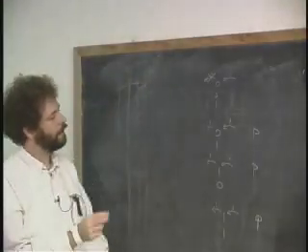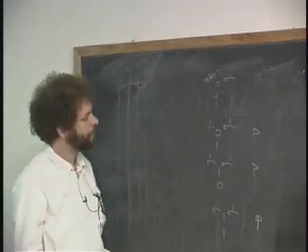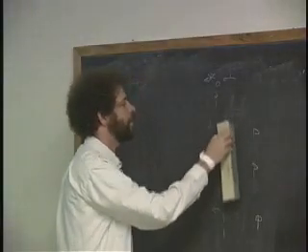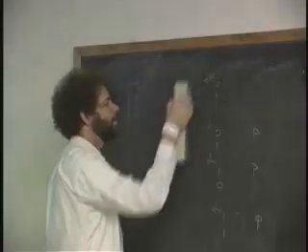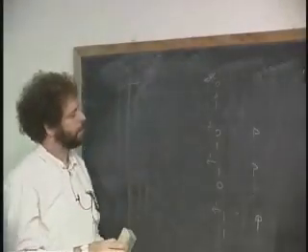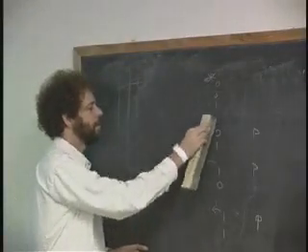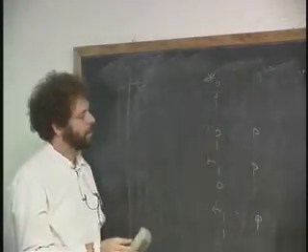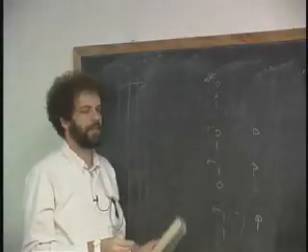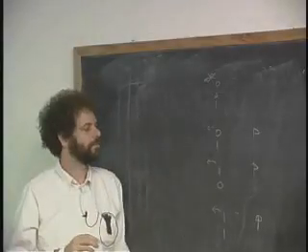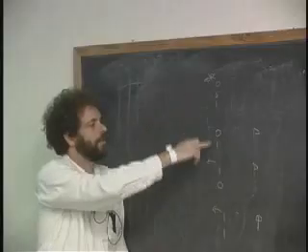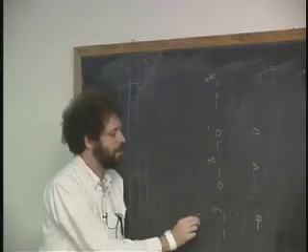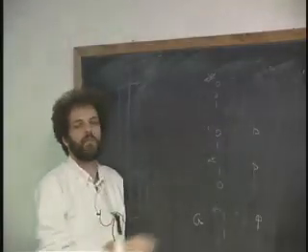Okay. Second question. Independent of what the carry in is, let's say I don't worry about that. I only worry about these bits here. In which cases, assuming that the propagation is handled in a separate way, in which cases here do I generate a carry, irrespective of what comes in? Here, no. Here, no. Here, no. Here, yes. Okay. So here I generate, and in those three cases I propagate.